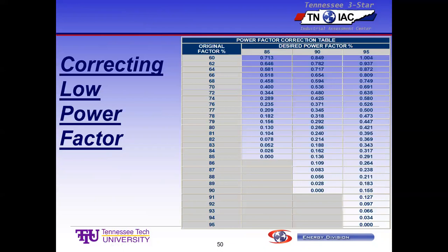So if I take 100 times that, that's about 69.1 kVAR. That's in the ballpark of what we were adding. I think we said add 67 or something like that in our calculation. So, kind of the lazy man's way of estimating this.